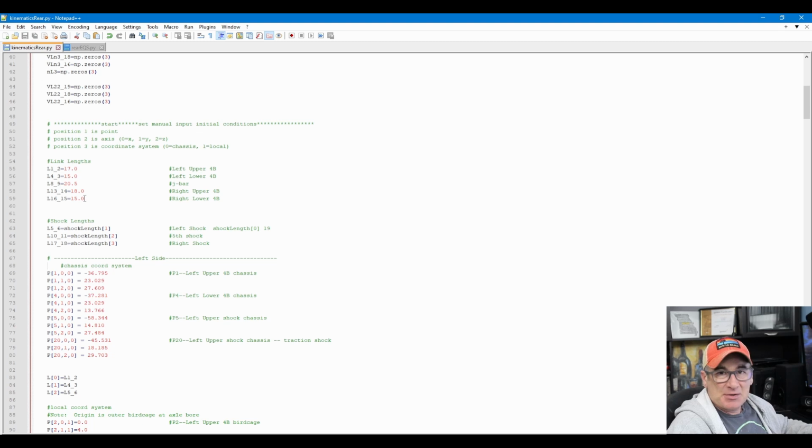We talked about making chassis pickup point adjustments. Well, link lengths are also very common adjustments, and so that's another parameter that we can assign to our model. But it's not an input to the model because it's not something that's going to change when we do our analysis. Once we set it, it's not going to move until we want to make an adjustment.